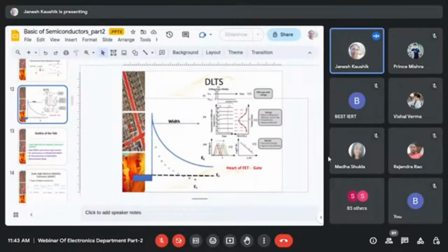Here it is an electron trap which is above the Fermi level, so it will not keep the electron, it will emit the electron, because thermodynamically it is not possible to trap the electron now. Due to that, you see a slight reduction in the depletion width in this figure animation. So that is the crux of DLTS.